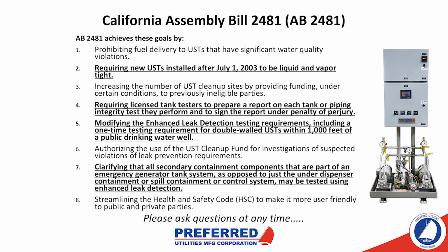Skipping down to number 7, clarifying that all secondary containment components that are part of an emergency generator system, as opposed to just under dispenser containment or spill containment or control system, may be tested using enhanced leak detection. So, in other words, not just gas stations, this is for everybody now.